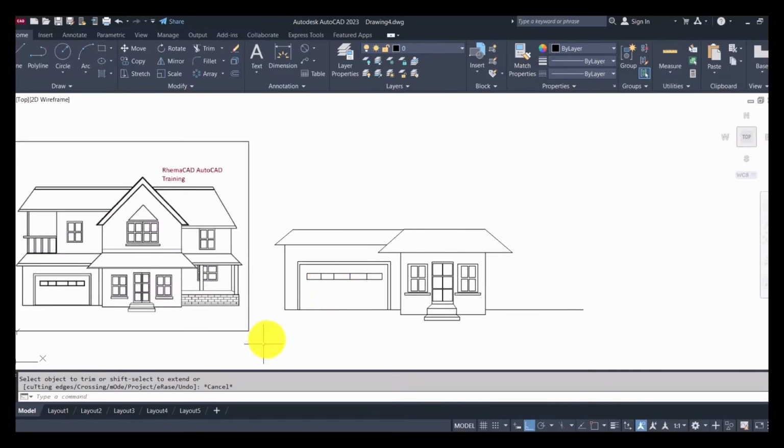Okay, so this is the garage with the windows. Then now I'm going to focus on my left hand side. So let me extend this line a little bit. Then before we draw the upper parts for the left hand side, I can see a rectangle below. So rectangle, object snap from here.